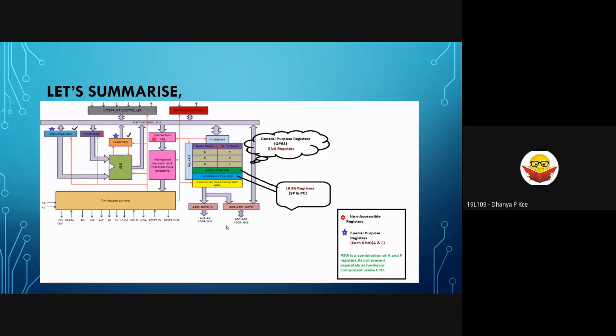So obviously, every memory location has to be incremented by 1, right? I fetch 21. I decode. Once I decode, I understand it is a 3 byte instruction. So during the next cycle, I will get the second lower byte. Then during the next cycle, I have to get the higher byte.